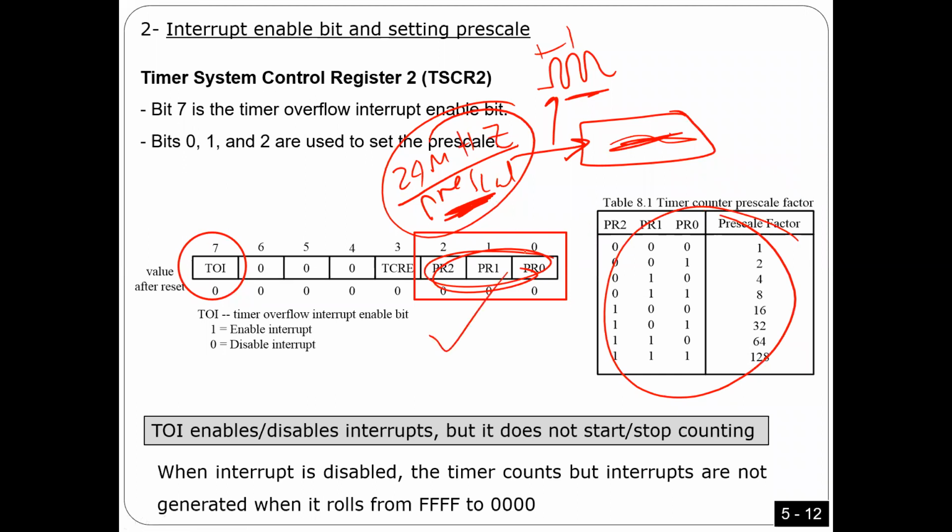Number two, any interrupt. That's why I'm telling you guys, nothing is new. For any interrupt, I have to tell you two things. As I mentioned before, for any interrupt, tell me where is the interrupt enable bit, and tell me where is the interrupt flag bit. Remember, the flag bit is the one you have to clear, right? So for the timer, because the timer is generating interrupts, any source of interrupt should have an enable bit and also an interrupt flag bit.